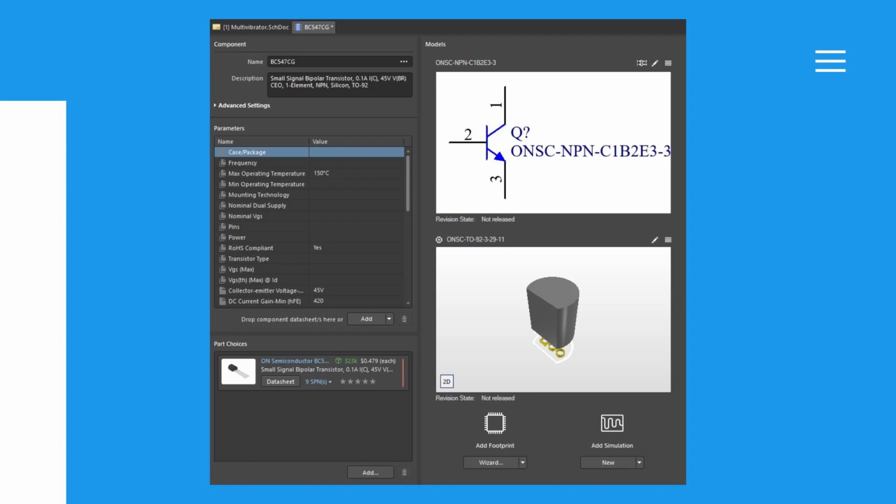The single component editor will open. With the chosen data loaded, leave the data values at their defaults and select File, Save to Server command from the main menus. Lastly, in the Edit Revision for Item dialog that opens, type in a meaningful comment to the component item revision release into the release notes field.